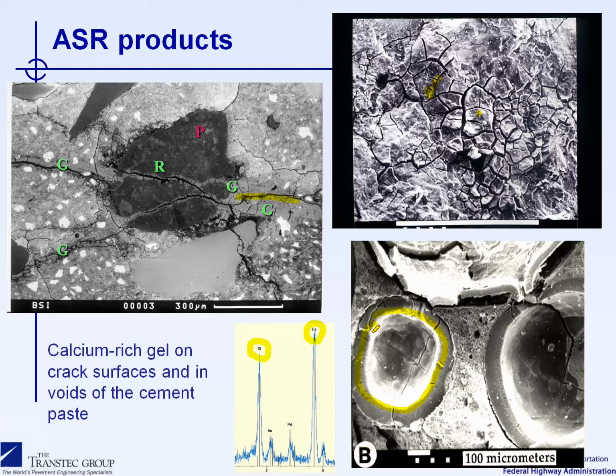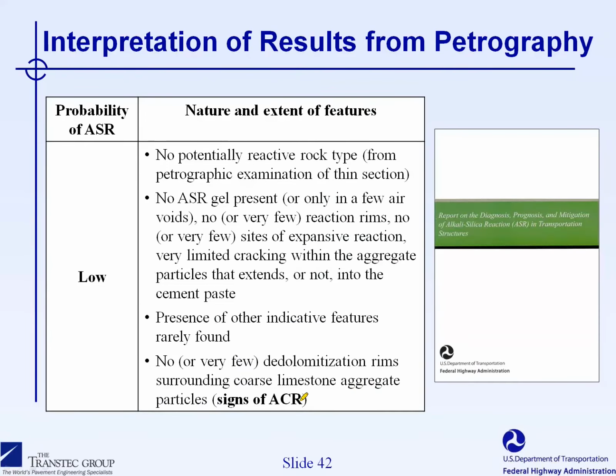So those are typical features of ASR that can be confirmed with the scanning electron microscope, where you can see the microtexture characteristic of the gel as well as the chemical composition to confirm that ASR is really the factor responsible for the cracking.